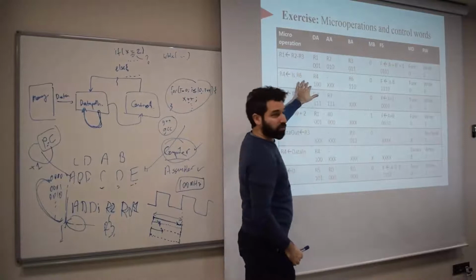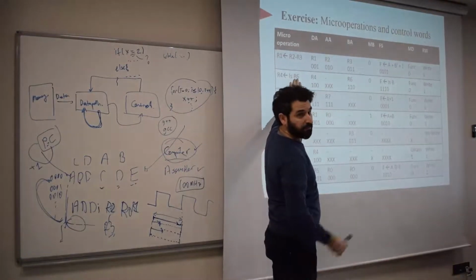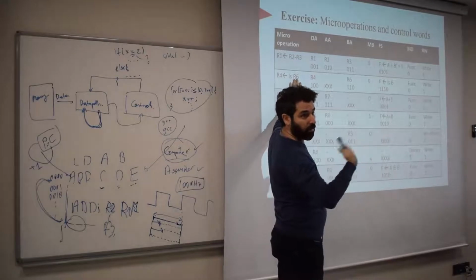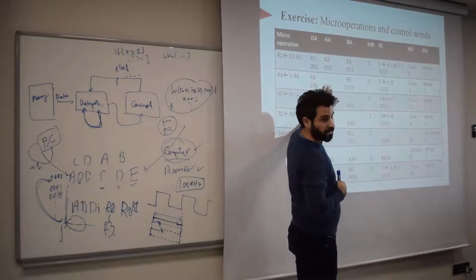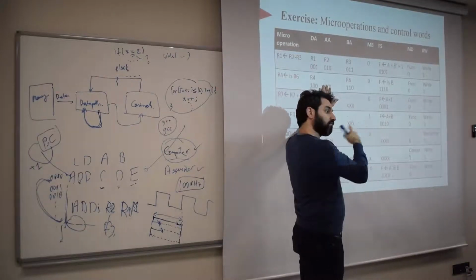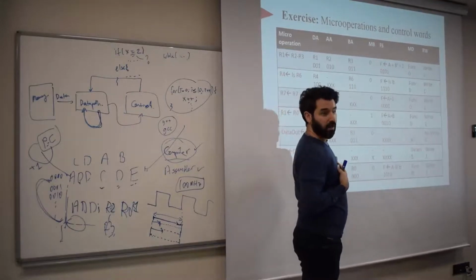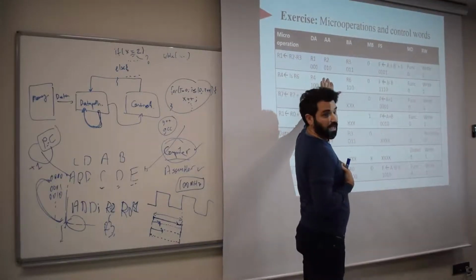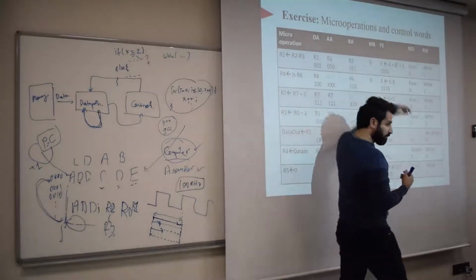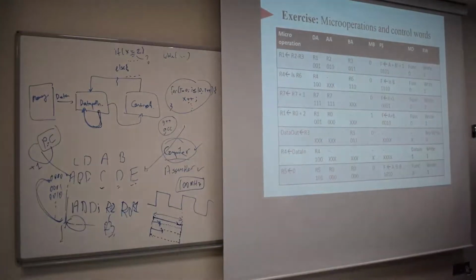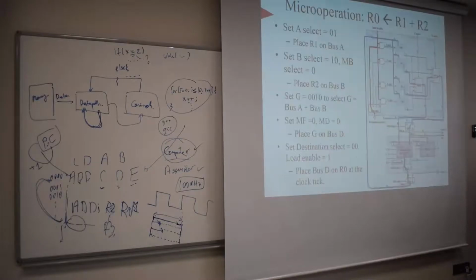In the left shift, there are 2 registers. One is the destination, you can see, and the other is the second operand, which we call B, but not A. That's why A is just empty. That's don't care. Okay? Again, you have to look at the data path in order to understand this. Our hardware does not allow us to use this operand for shifting purposes. The shifting happens only with B. Okay? How did I understand that?